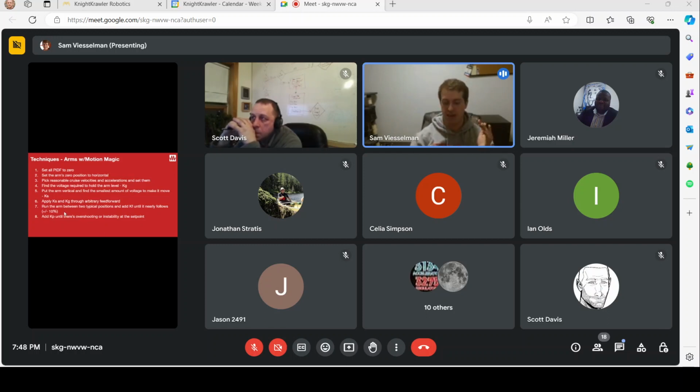So once we have KF tuned in, we're following the path pretty well without any feedback at all. We've done no PID at all. We've just canceled gravity, canceled friction, and got our feed forward going. And then the last part is adding KP, just keep cranking it up until you start seeing some instability or overshooting, and then you back it off until you don't.